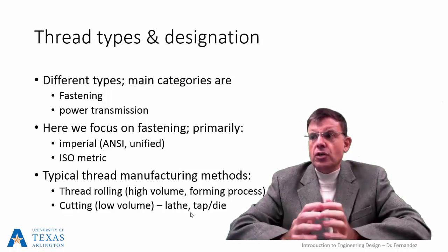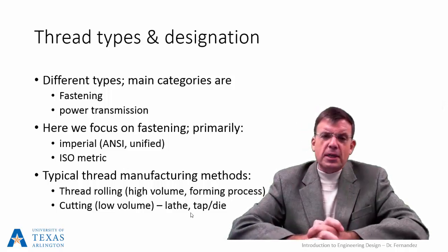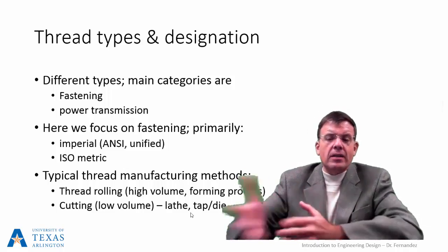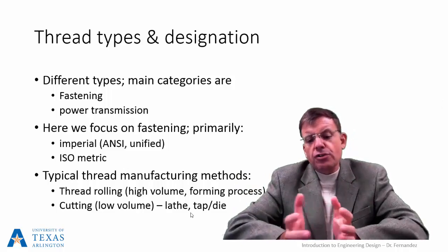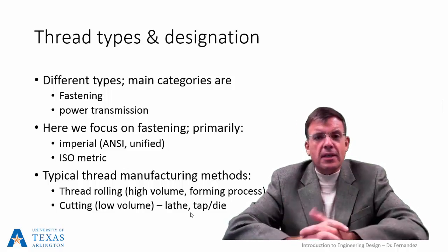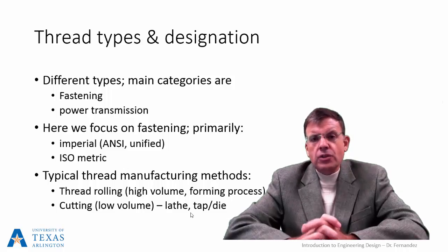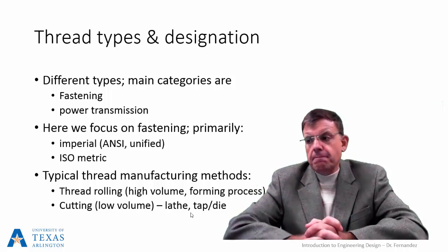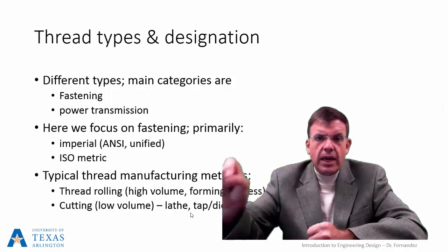All right, so standards. So whenever we talk about components like these, you can rest assured that there's going to be a standard availing the particular set of dimensions that they conform to. Okay. As usual, here in the United States, we have to live with our own homegrown standard, so the American standard, and then of course the international standard that generally tends to be under the banner of ISO. Okay, so our homegrown or imperial standard is known as the UN Unified National Thread. Okay, so you will see the UN, then C for coarse, and UNF for fine.